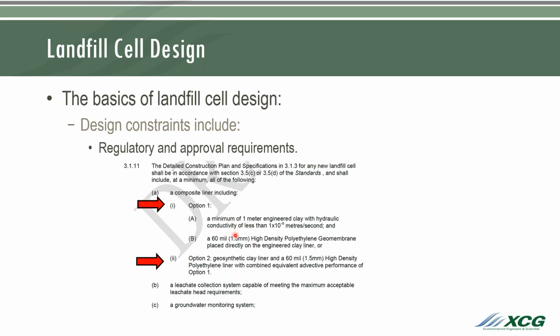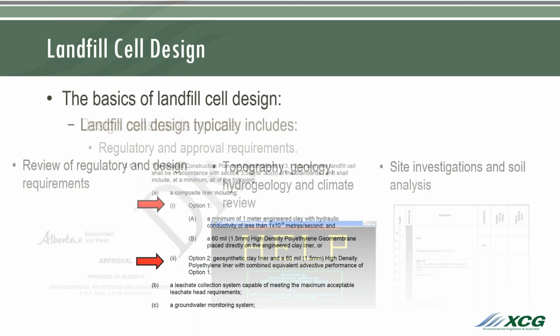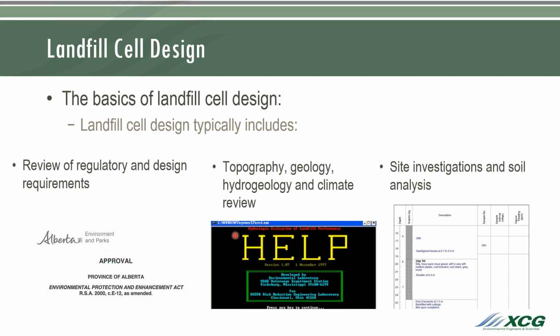So a lot of places, they'll end up going with option 2 just to get that 1 meter across your entire cell back as far as airspace. So these are items that we typically take into consideration when we're looking at the design of a landfill cell. So obviously your approval, which basically guides you step by step the items that you need to consider